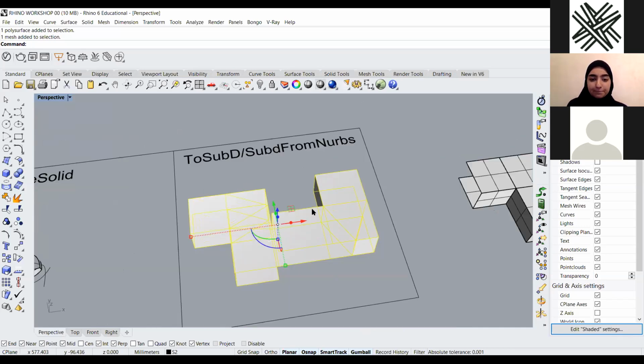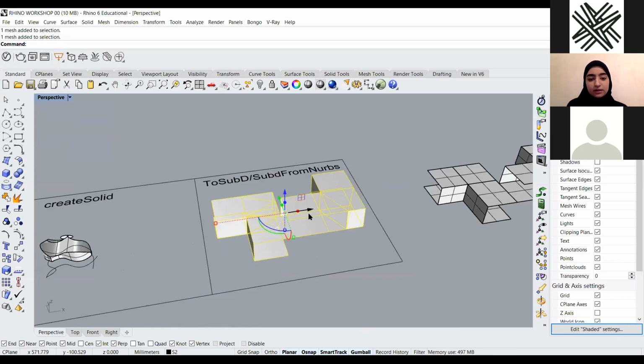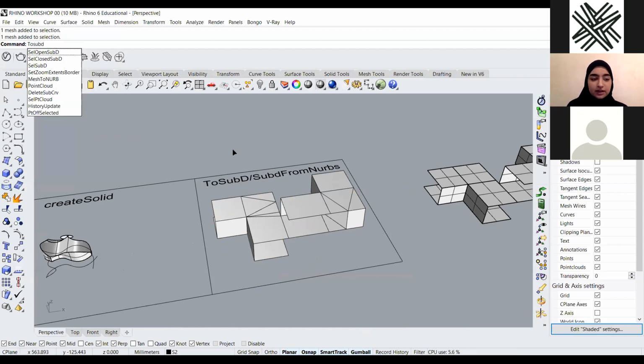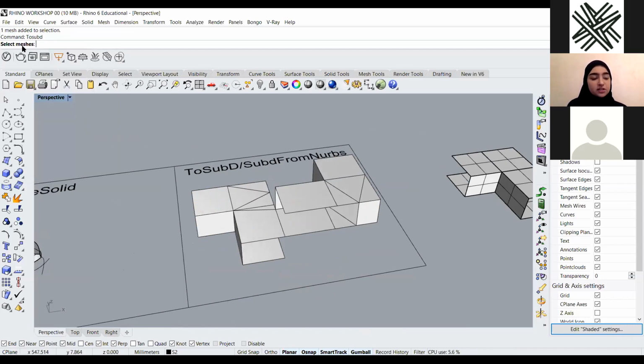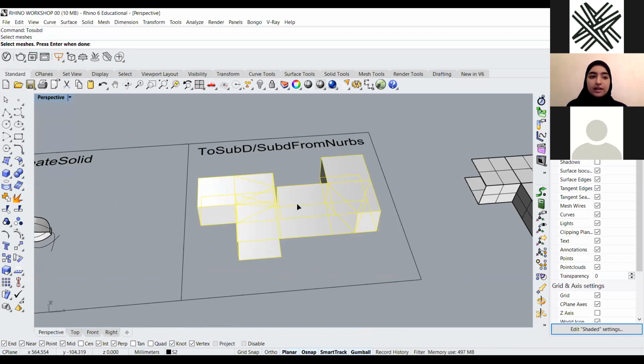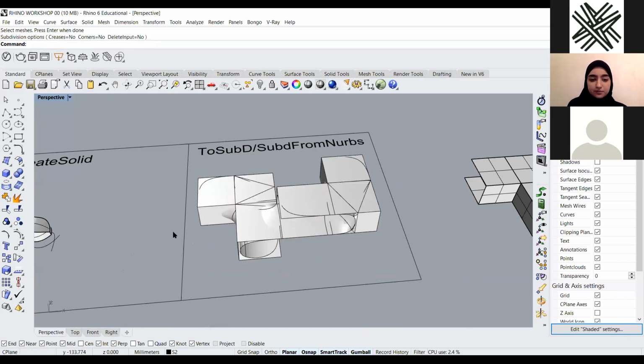Okay. So now I'm gonna type ToSubD, enter, and then it's gonna ask me to select meshes. So it works only with meshes. Then I'm gonna select my mesh and then enter. So keep these options, no, and then enter.